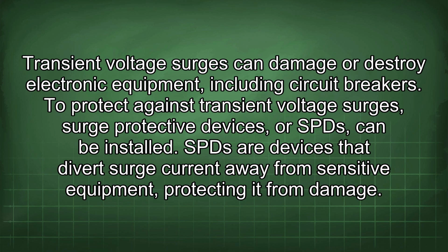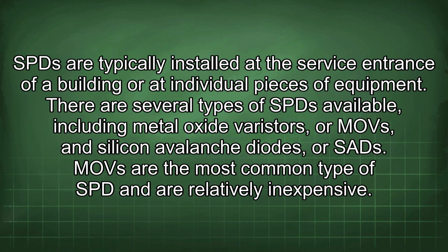To protect against transient voltage surges, surge protective devices, or SPDs, can be installed. SPDs are devices that divert surge current away from sensitive equipment, protecting it from damage. SPDs are typically installed at the service entrance of a building or at individual pieces of equipment.